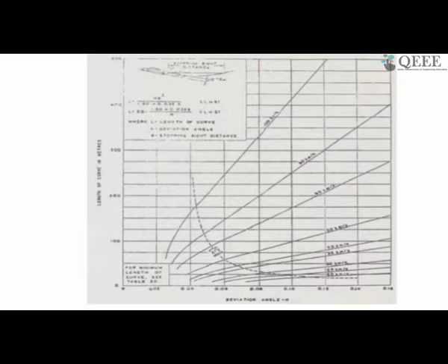The headlight sight distance is not for the glare from the opposite side. It is the headlight of the vehicle which is traveling falling on the road; only then can they see the road, and then the vehicle can travel. So it is their own headlight, not the other headlight. The small trees or the shrubs you provide along the median only help with the glare coming from the other side. So that is a different aspect altogether. That is not part of this design.